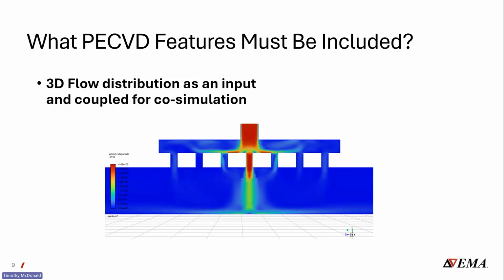First, that neutral gas flow controls the plasma uniformity and reactant supply. So those neutral gases that come in the chamber through the shower heads, they're carrying the precursor molecules, silane, ammonia, oxygen. If the flow is uneven, some regions may get more reactants than others. Depletion effects at high aspect ratio or large wafer processes: precursors get consumed along the way.